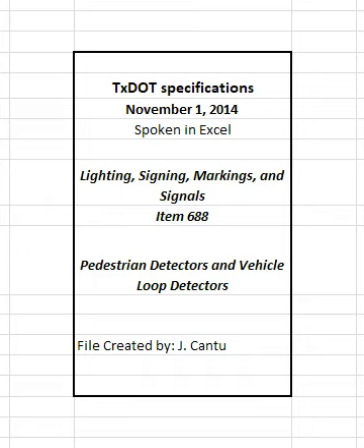Close unused housing openings with a weather-tight closure painted to match the housing. Verify that each button is communicating and fully functional. Do not use terminal connections or splice wire leads except at approved locations. All allowed splices must be watertight. Attach wires to terminal posts with solderless terminals unless otherwise advised by manufacturer's recommendations. Attach terminals to the wires with a ratchet-type compression crimping tool properly sized to the wire.